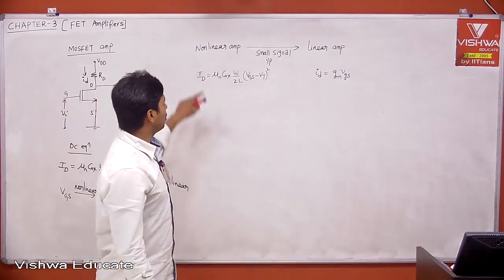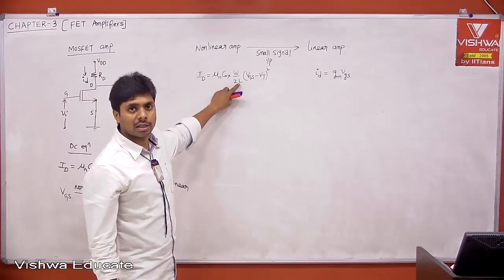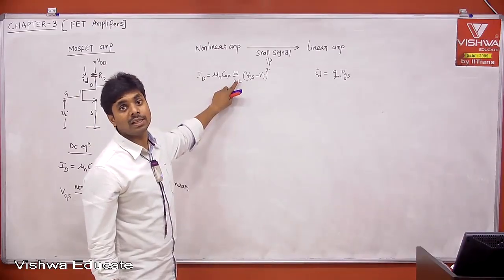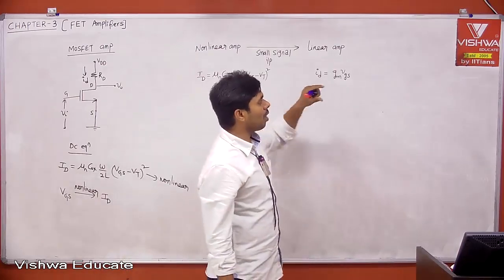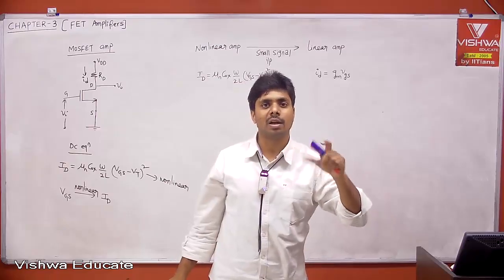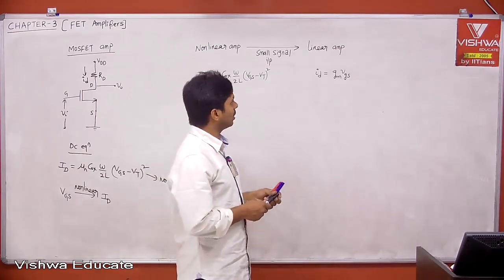Even though the DC relationships are fundamentally non-linear, it doesn't matter. For biasing, keeping the transistor in the saturation region, and Q point stability, we are not doing any DC signal amplification. We are only doing AC signal amplification, and that too must be a small signal. If you apply a large signal to an amplifier, you will get distortion, harmonic distortion. You understand the point?